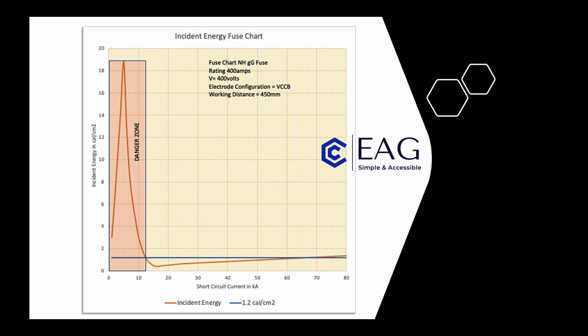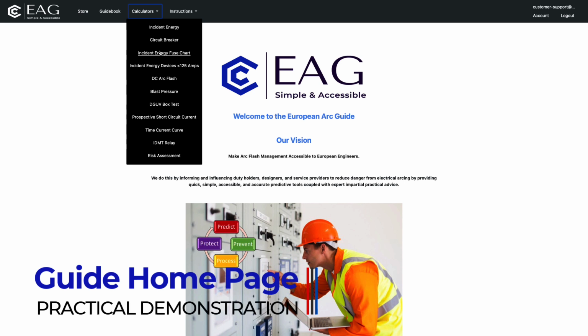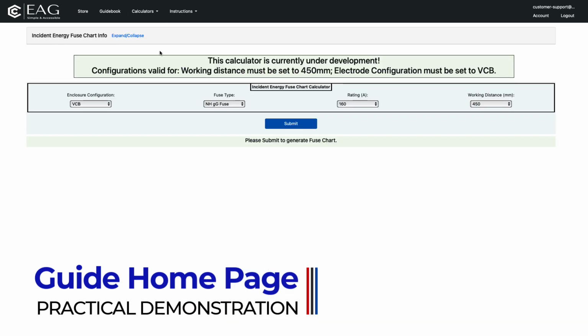This is derived from a calculation of arcing current and the corresponding determination of disconnection time. This provides a basis for incident energy levels to be established over the fault handling capability range of the fuse. In this case, it's based upon a working distance of 450 mm between the source of the arc and the worker. To access the charts, select the Calculators tab and then Incident Energy Fuse Chart.